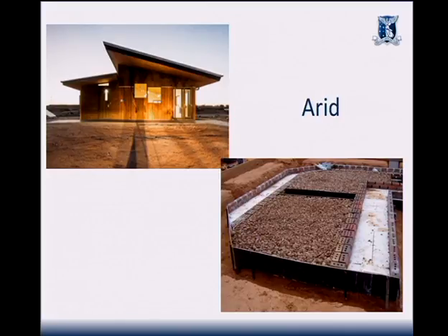Why would you have a rock bed? What's the difference between a rock bed and thermal concrete? What's the actual difference between a whole pile of rocks and one solid thing of concrete? Yeah, okay, surface area. So more air gets across all of the rocks and cools them or heats them more effectively.